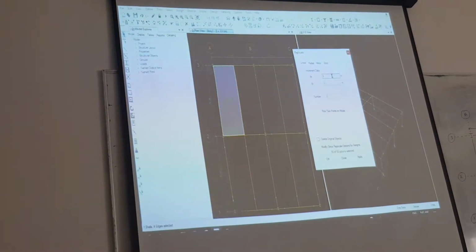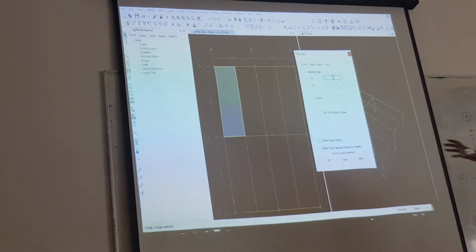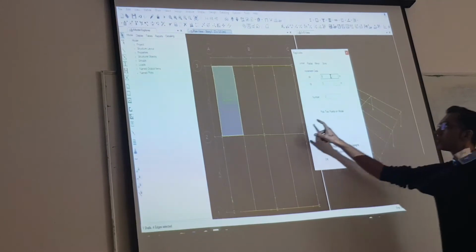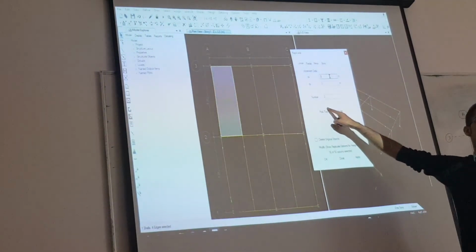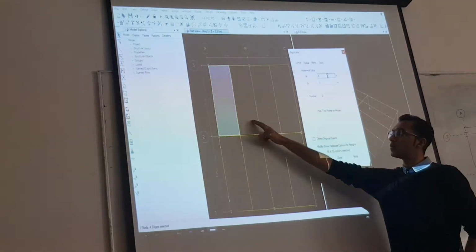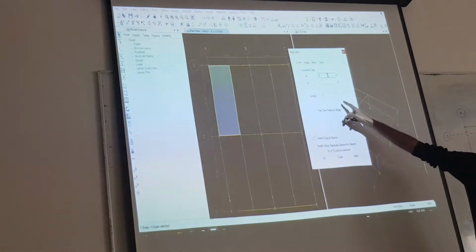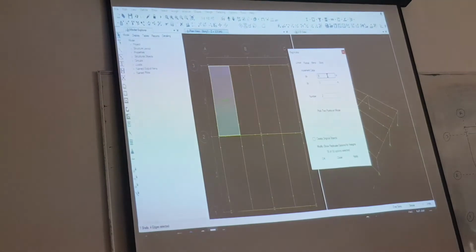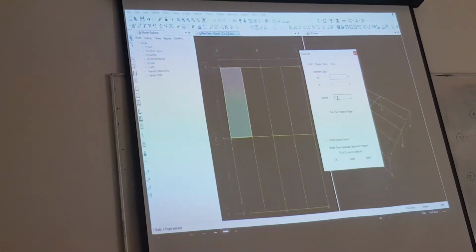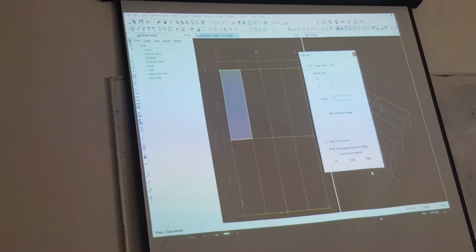If you see that in the other part of the grid system the dimensions are symmetrical, you can increase the number of replicates. So it means that we are going to replicate it 3 times, 1, 2 and 3. So simply you can type 3 over here, and apply it.